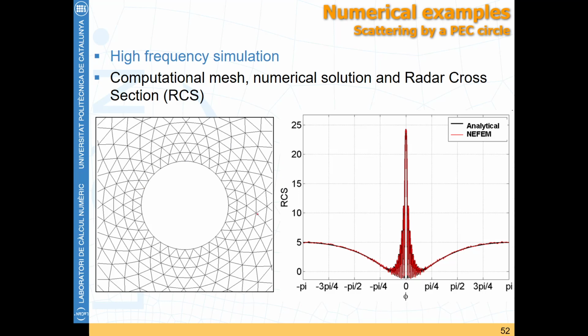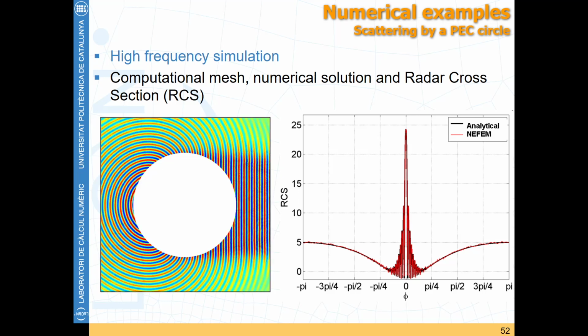So in electromagnetics, geometry matters, as we saw in the applications, in how it scatters the field. You see a profile of this higher frequency. So in fact, it is of interest to have one element that is able to capture all these wavelengths, all these oscillations. With these much smaller wavelengths, you need smaller triangles, right? So that's why you needed this finer mesh.